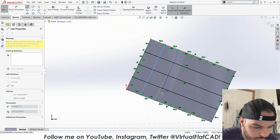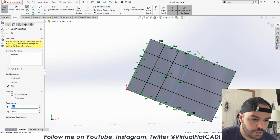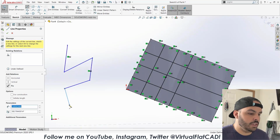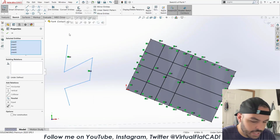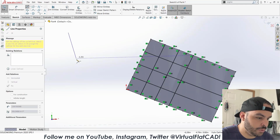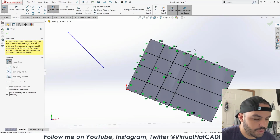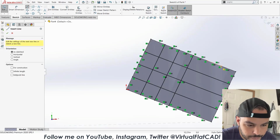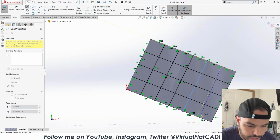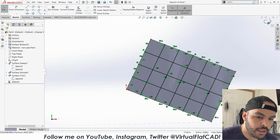Draw that and there. And a cool thing that I'm doing is that normally when you draw a line, if you click to click, you get this whole chain. But very subtly, if instead you click, hold, and drag, it gives you one line and automatically terminates it. So when you're doing something like this, it's a nice little quality of life improvement, so I don't have to keep hitting escape to terminate the line over and over again.